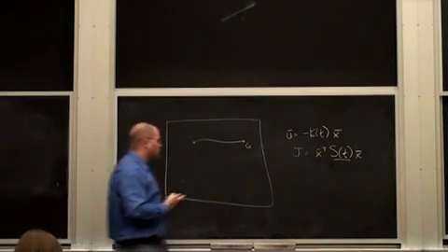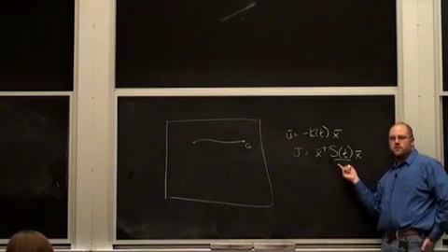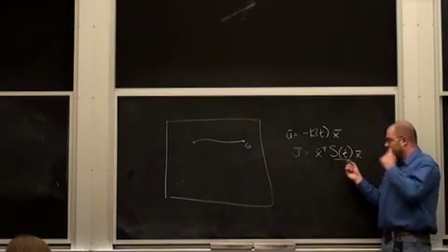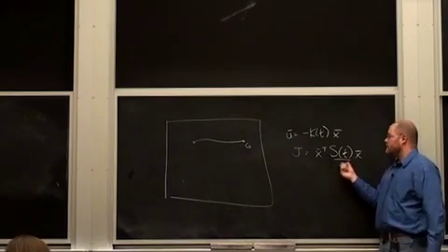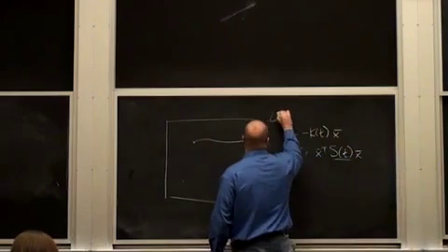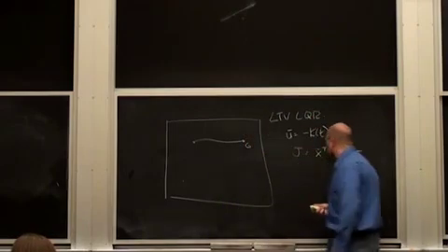Because of that, when we're doing our LQR design, we actually have a good candidate for a Lyapunov function for the system around that trajectory. So that's an important observation, that when we do LTV LQR on a trajectory, we get both, okay?